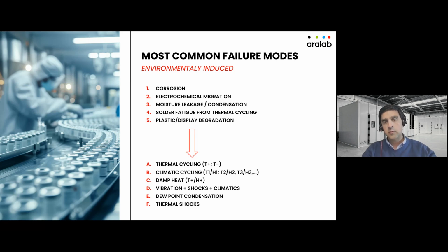And some of the tests that we conduct, or that our users conduct, better said, are listed below. Okay, so thermal cycling, of course, this is by far the most common one. So thermal cycling is exactly what it says on the tin, which is submitting a sample to cycles of high and low temperatures. Okay, it's very important that of course, in an environmental chamber, we control the air temperature, but it's very important to note that we may also add additional sensoring to control the temperature at the sample.